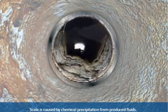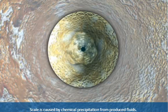Scale is caused by chemical precipitation from produced fluids. This is just like limescale in a kettle. Scale buildup will eventually stop production, as the deposits can coat perforations, casing, and production completions. Scale may be removed either mechanically or by dissolving it.